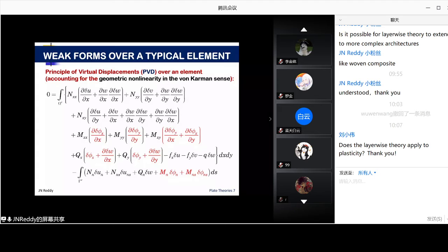All right. Yes. Okay. So now you see the variables Nxx, Nyy, Nxy, Mxx. All of these are known in terms of strains, which are known in terms of displacements. So this is a very short way to write it. But if you express all of them in terms of displacements, the equations become larger, and I'm going to show you a few of them.